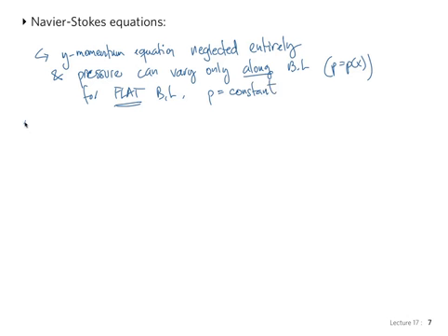So what do we have finally for our Navier-Stokes equations with all of these additional assumptions? We have continuity. We never can get rid of continuity because mass has to be conserved. And only the x direction. For the x direction, remember, P is going to be a constant for the flat case, and so pressure drops out.